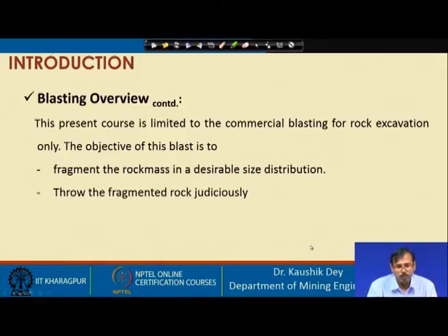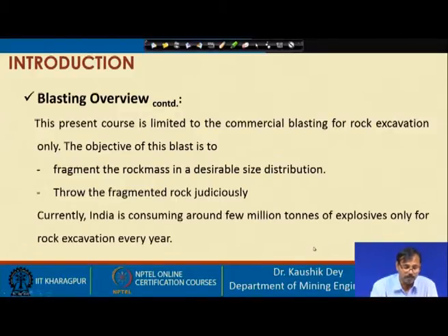We want to throw the rock also, so that it is fragmented and dislodged or moved a little bit, but we do not want it to move a lot. We want the fragmented rock to move a little bit, so that some loading or gathering machine can come and take it out for the next processing or handling of the fragmented rock. So, this throw of fragmented rock is wanted, and it is wanted judiciously.